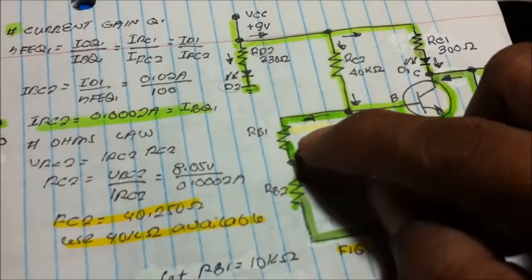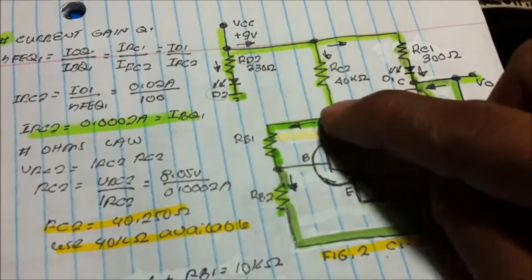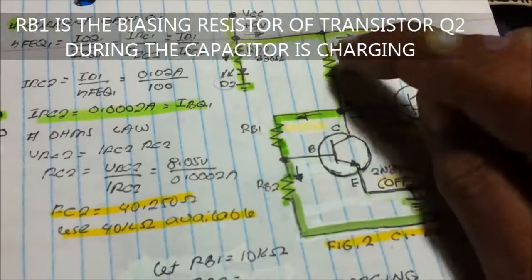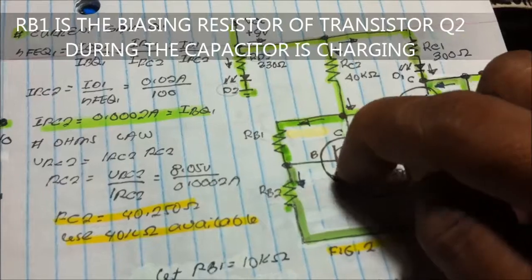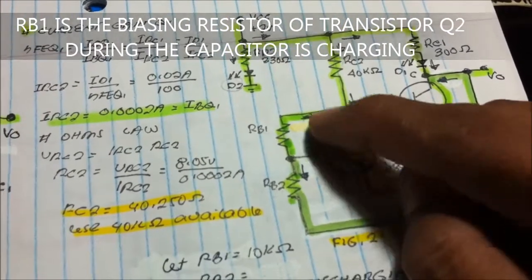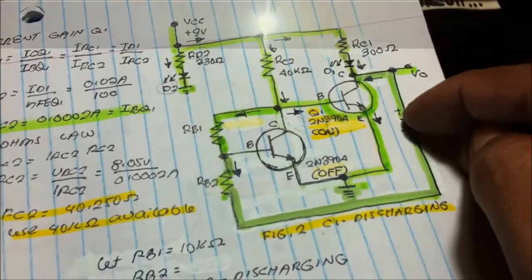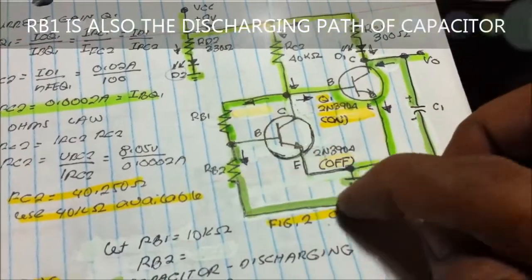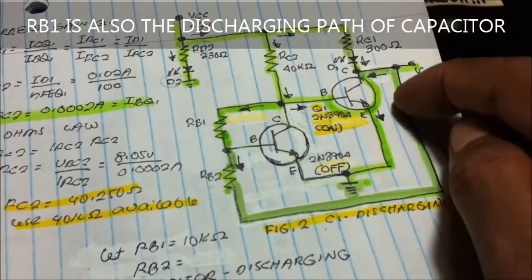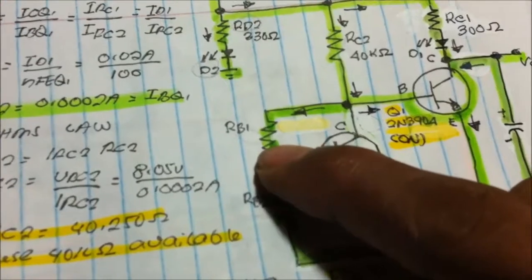How about this one? Why did I put a resistor here? So this resistor is some sort of coupling resistor that will serve as biasing of the transistor, at the same time the discharging path of the capacitor. What is the value of this RB1?